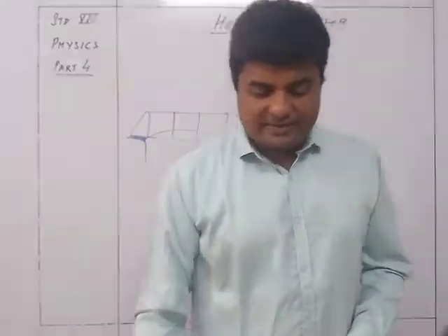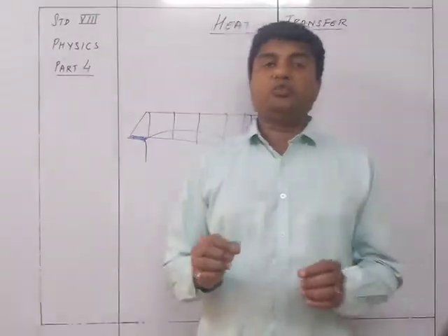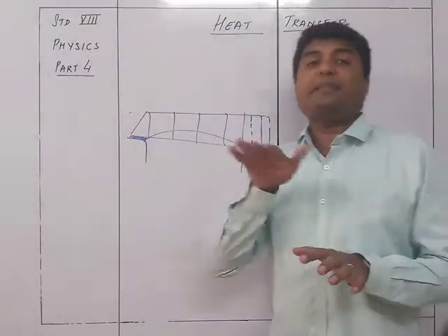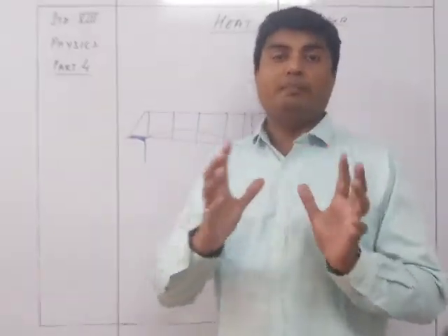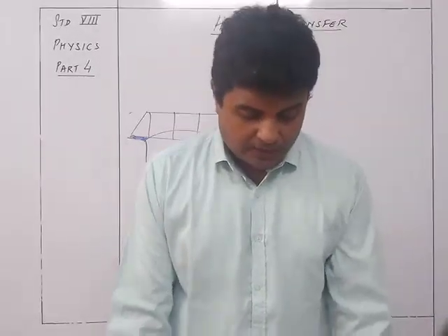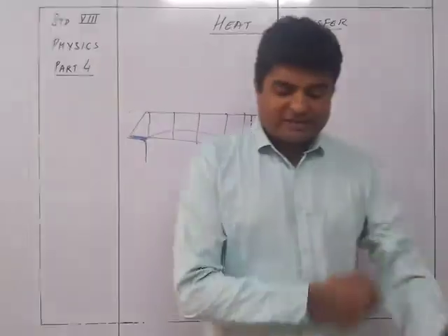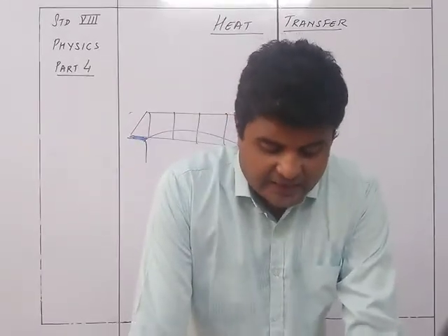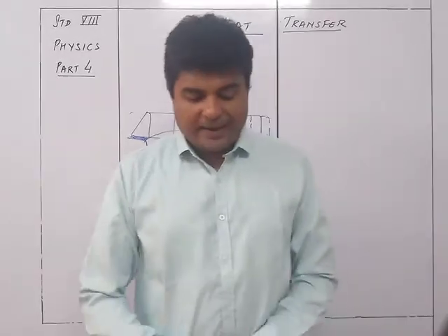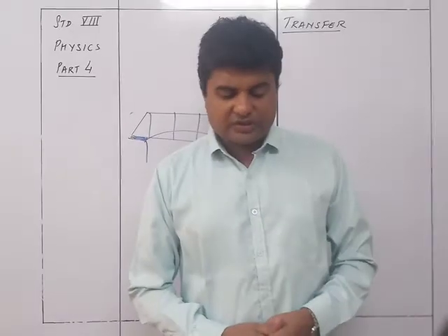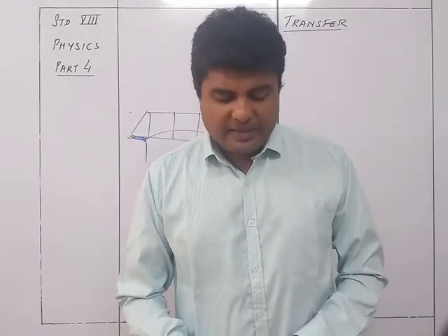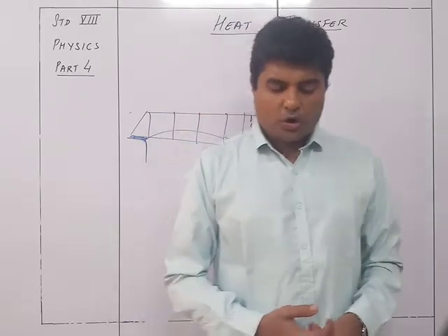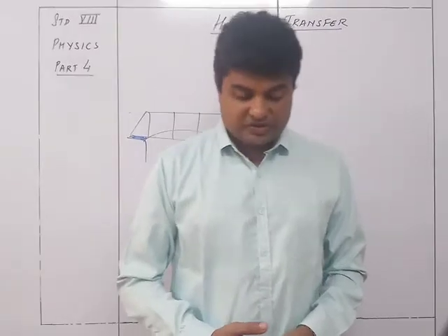So that's the reason it's important that the bridge will be such that one side it is fixed and the other side it is kept flexible so that it can be moving. So that's about the construction of a bridge. In the construction of a bridge, steel girders are used. One end A of the girder is fixed to the concrete, but the other end B is not fixed into the concrete or pillar. It is supported on rollers as shown in figure 6.7.